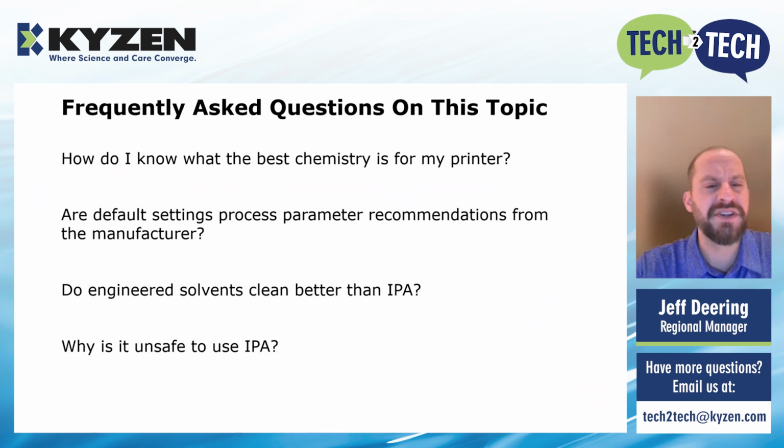Third, do engineered solvents clean better than IPA? Absolutely. An engineered solvent will help your printer process compared to the IPA every time. And why is it unsafe to use IPA? Well, first and foremost, it's very flammable. But it also does not solubilize paste as well as an engineered chemistry with current paste technology.